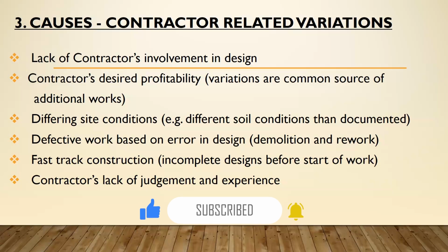And also where we have differing site conditions, which are different from the soil condition that was documented, it also gives rise to variation. Defective work based on error in design: the contractor has gone ahead to do the work before the design was concluded or completed. So this may call for either demolition or rework, and this also brings about cost.